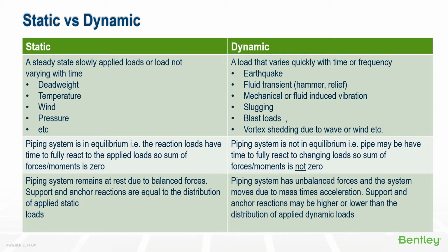thermal expansion or contraction. The behavior of frictional supports is considered nonlinear because of the complex interrelationships between support forces and the corresponding displacements. This frictional resistance may provide the additional restraining force needed to properly support the piping system without adding more supports. Soil yield also produces a nonlinear effect because the resistance of the soil changes with the intensity of the applied load. Once the load on the soil has passed its yield limit, it offers very little resistance. And you can refer to the buried piping training for more information on this topic.